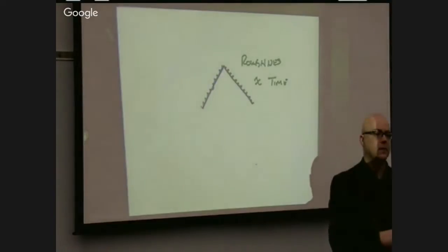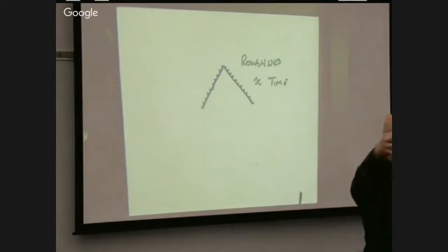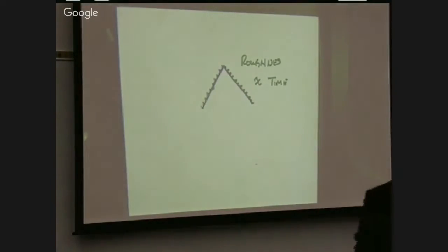Is there a tolerance we had to adjust at some point? So there's a tolerance setting in the software, and you may have had the tolerance set to a bigger number, which allows it to calculate the tool path faster, but then it doesn't control the tool as precisely. So that could be it. It could be the tolerance setting.